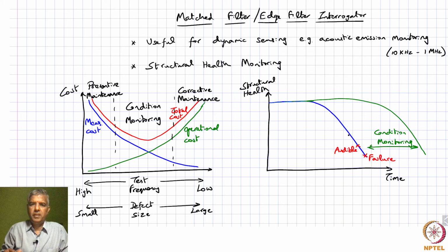And even before that, you could actually get some thermal signatures, right? If some moving part is developing a fault, maybe it will heat up a little more compared to other parts. And so if you're measuring temperature, you can say that this part is going to fail if it's operated like that for further time.